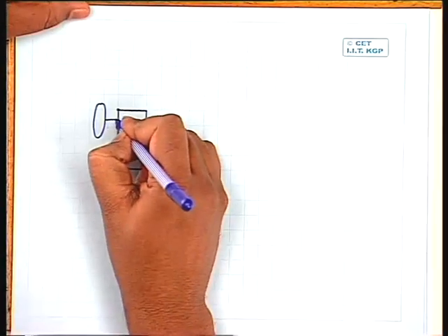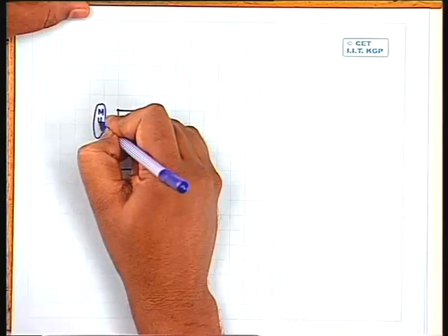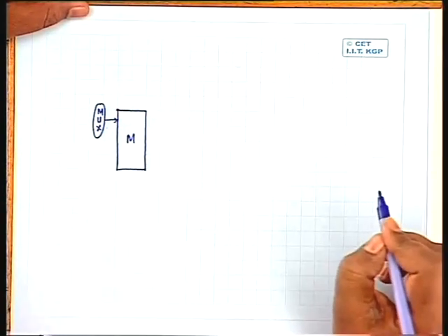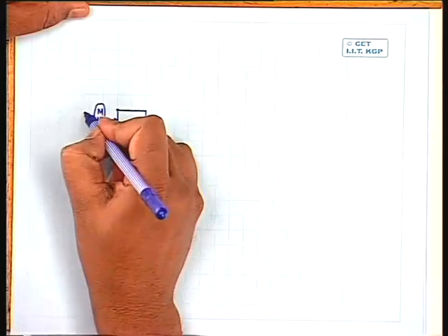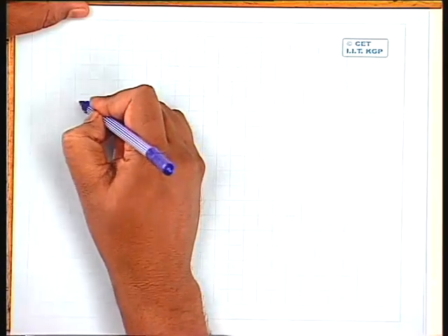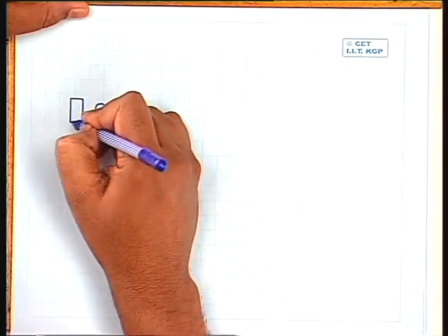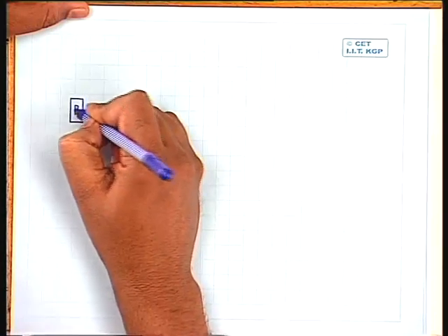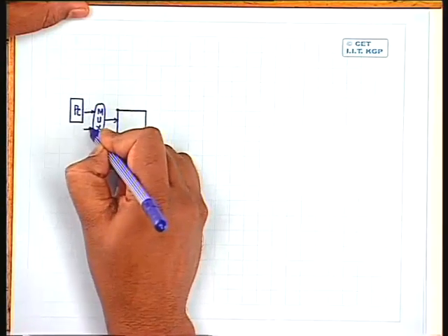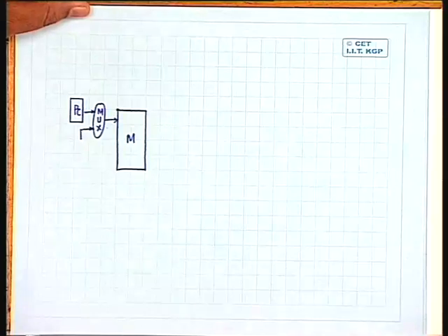So we have a multiplexer, and the multiplexer output gives the address of the memory. We will have 2 inputs to this multiplexer. One input will come from the program counter, and the other input will come from the ALU output. So we will connect this later.